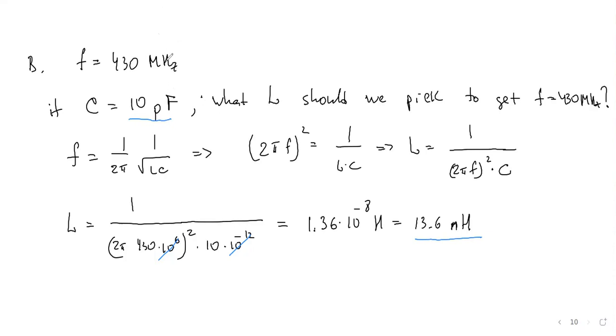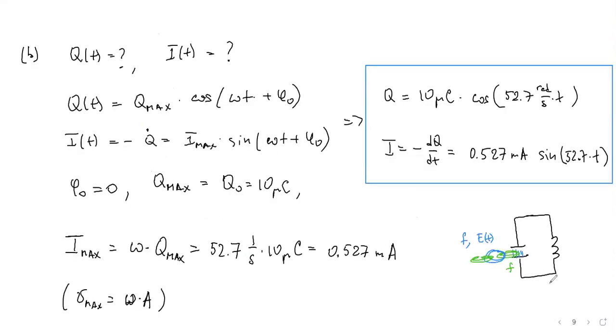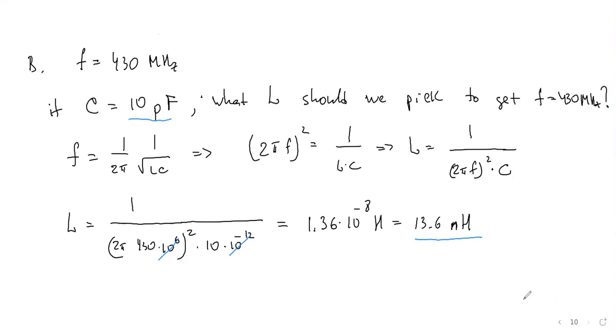Does it make sense? And usually you use this type of LC circuits in radio receivers. So if you want to tune to, I don't know, your favorite radio station, like 100 megahertz, then you can have a resonance of your LC circuit with the external signal. This would be interesting maybe to mention.